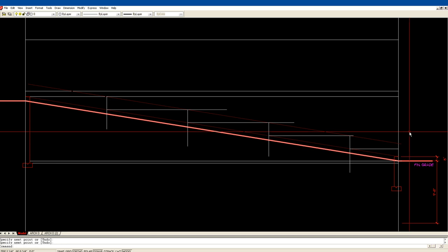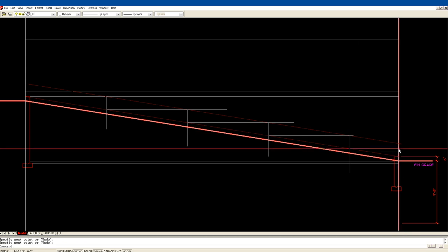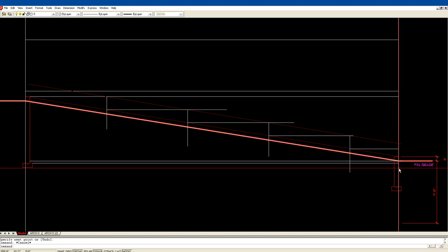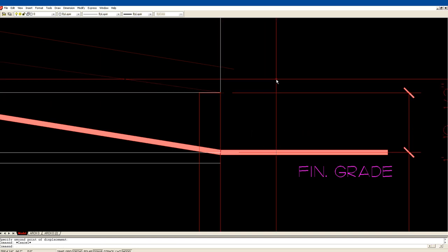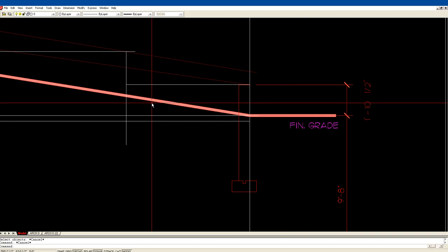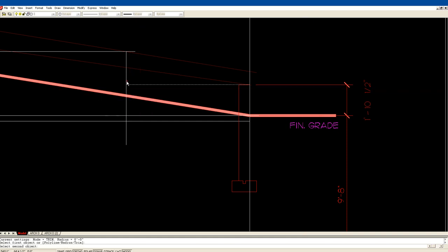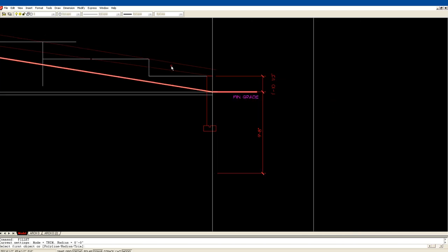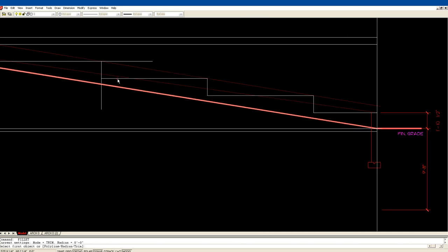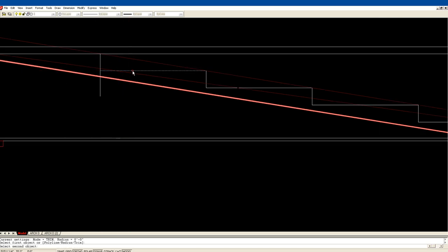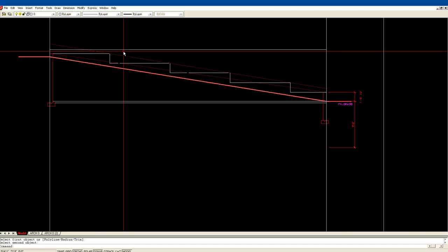Typically at this point he's going to have a lot of concrete showing. There's just nothing we can do about that. He can make another jog farther along this back wall to get down to that height, but at this point we're just going to stretch, and we're just going to go right up. That's where we say everything's going to be right now. And fillet. So there I'm 8 inches away with my concrete. Fillet all of this. Fillet, and again.